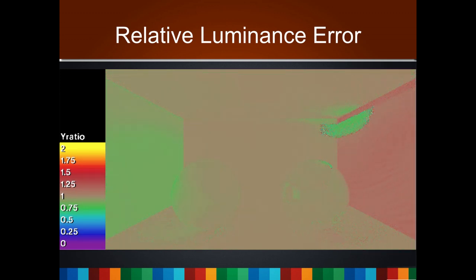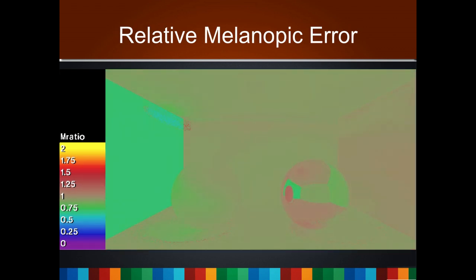You can see it's within about 20%, even with RGB calculations. But 20% is kind of the limit of where we want to be with daylight calculations in the first place. So this definitely gets us more accuracy. And then we have melanopic error, which ends up being larger than the photopic error was. So that lends credence to people's belief that melanopic is a little more sensitive to spectral than photopic. It does seem to be from what I've seen.